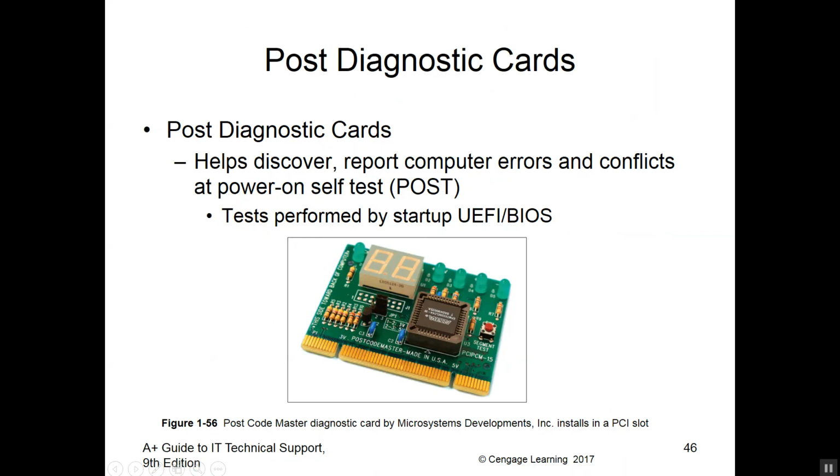Okay. Now this one is a post-diagnostic card. It helps discover and report computer errors and conflicts at the power-on self test, or POST, a test performed by startup and the UEFI and BIOS. It's a great little diagnostic.